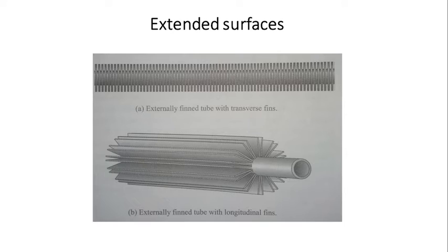So this is the figure of fins, which is the extended surface. So the fins provide a greater surface area. So the overall external heat transfer coefficient can be enhanced by using these types of extended surfaces. This increases the rate of heat transfer per unit length of the tube.